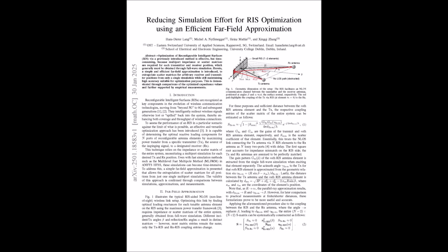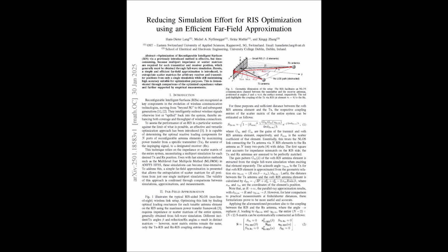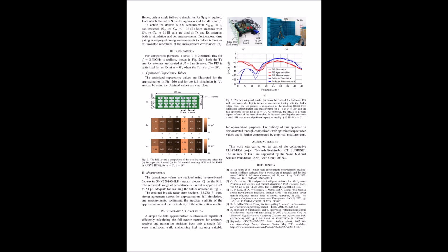Makes sense. What about those Gs? I see G_TX and G_m. Right. So G_TX is the gain of the transmitter antenna, basically how effectively the transmitter antenna can radiate power in a specific direction. Okay, so a higher gain means a stronger signal in that direction. Exactly. Now, G_m is a bit more interesting. How so?